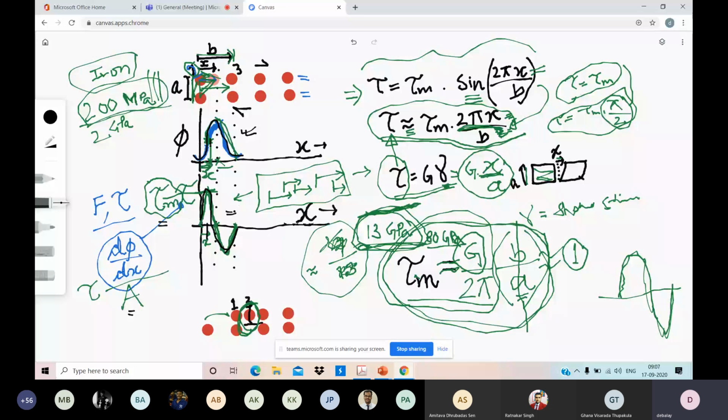That is a sufficient distance x where you just cross the elastic regime, and as you cross that elastic regime with sufficient stress, you make sure the atom will move into the next equilibrium position. And by this process, you will find an extra atom will situate somewhere in between and a dislocation will be created. So what we are talking about is the creation of a dislocation by the application of shear stress. By the application of shear stress tau, how much stress is needed to create a dislocation.